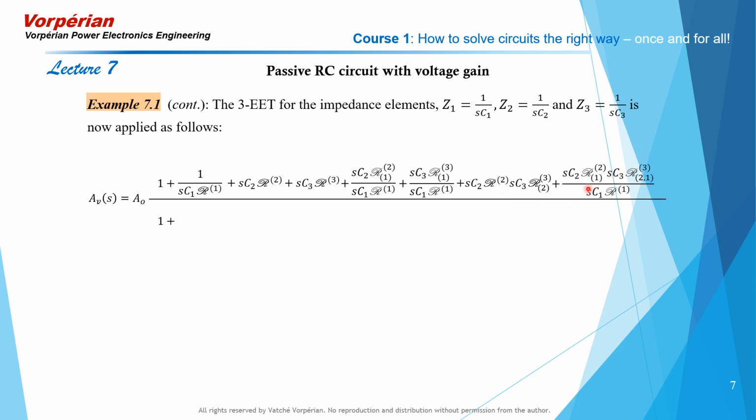And then finally, we're going to bring all 3 together at the same time, and the order in which we bring them is not important. z1, z2, z3, z2, z1, z3, z3, z1, z2, whichever way you bring them in. So when we first bring in z1, it comes in just like it was here all by itself. Then we bring in the second element just like it was here in this pair of 1 and 2, looking into port 2 with port 1, the port that it is being paired with, in the opposite state of its reference state.